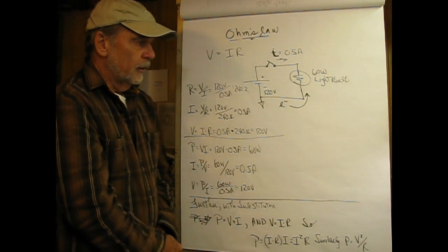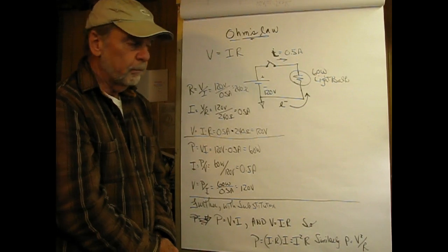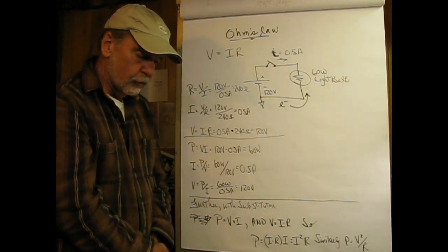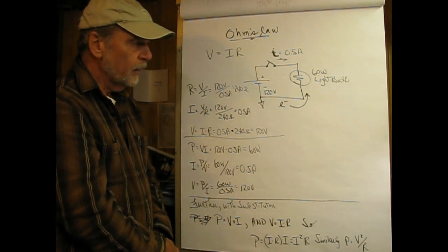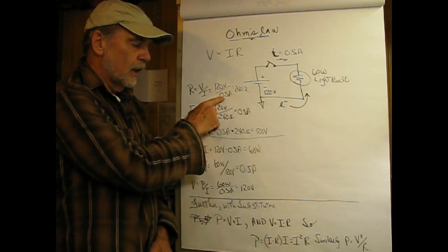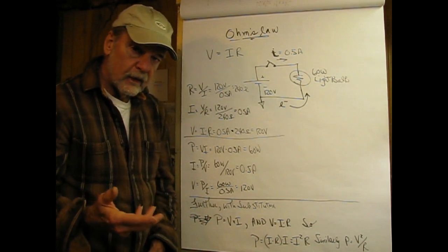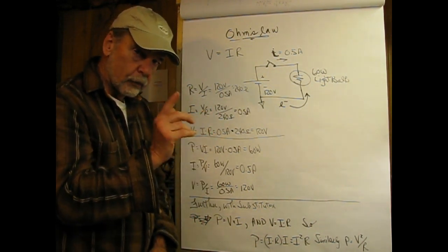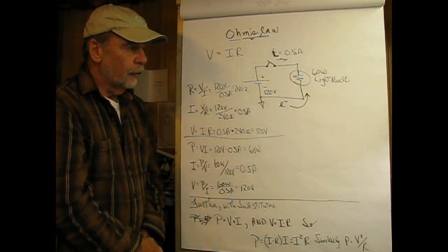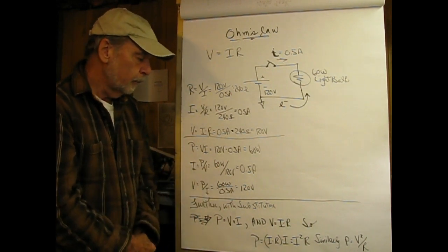Now I'm telling you a little bit of a lie here. That 240 ohms occurs when the filament's hot. Tungsten has a very nonlinear resistance relative to temperature, and the input surge to this can offer a current flow of approximately 6 times 0.5 amperes. And that's why a lot of times the light bulbs burn out when you turn them on. It's that surge of current that causes them to fail. Further, the filament is eroded on the sides, but we won't get into that right now.